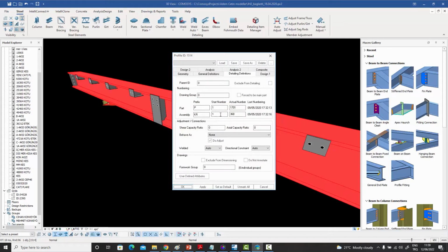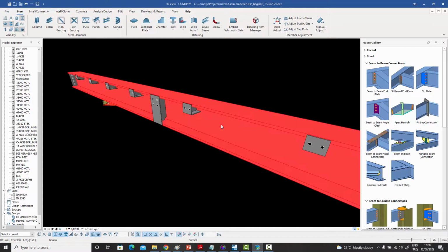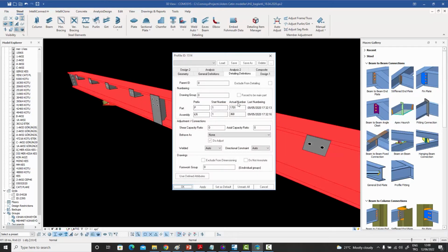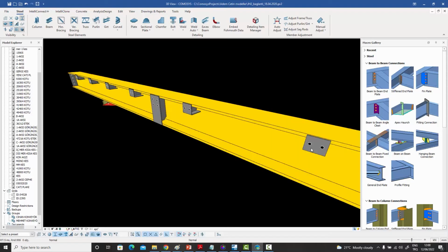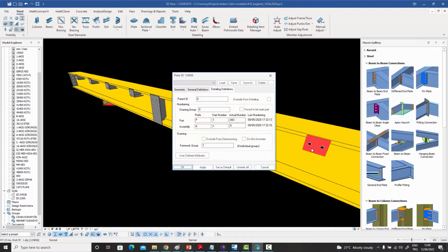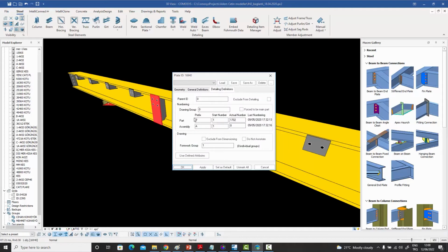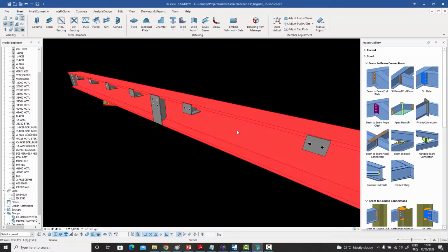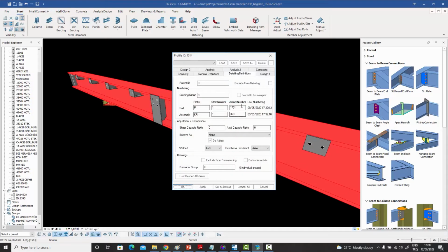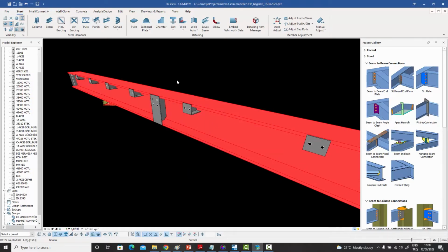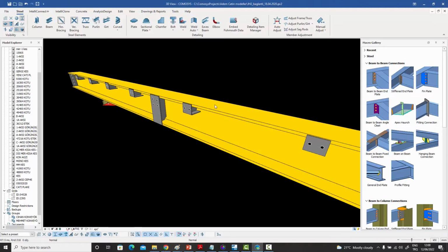In steel structures, basically every part has a part mark, like we talked about. So if they were going to manufacture only this beam, not the parts welded to it, then they would be manufacturing the part P1701. If they were to manufacture only this plate at the shop, they would be manufacturing P493. Or similarly, if they were to cut out this part, they would be manufacturing P1702. But when they would be manufacturing the beam KR368, then they would put all these parts together and they will have a drawing, and the dimensions will be given on that. And that will be called the assembly drawing of this beam.